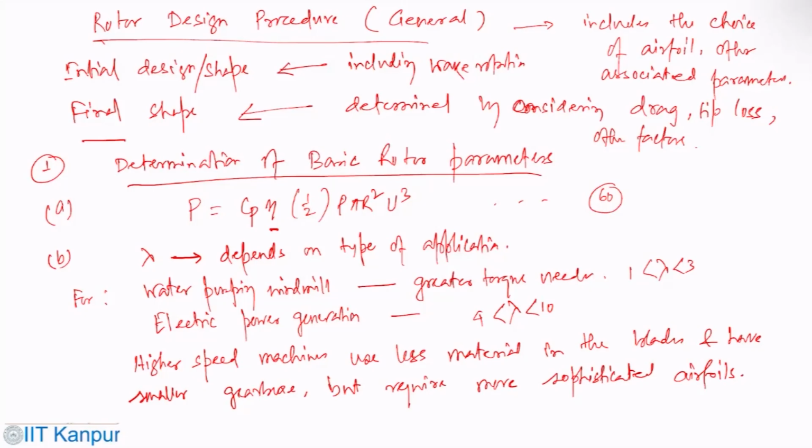Now you need to choose the number of blades, which is B. If fewer than 3 blades are selected, then there are a number of structural dynamics problems that must be considered in hub design.